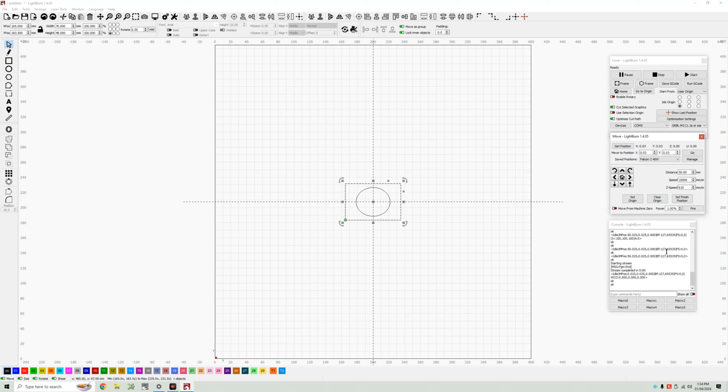So anyways, that's how you set it up, and then just leave this wherever you want to leave it, and just know that it's going to start right there on your machine once you have it set to that point. If you set that point up here, it'll start right here. You could set it anywhere, and that's where I think they did kind of a not great job of explaining the use of it, and even in LightBurn's tutorial, I had to kind of wrap my head around it. But where it really comes into its own is being able to use the center point to align everything.